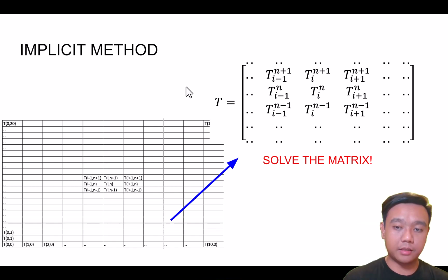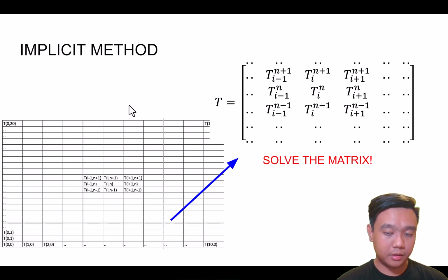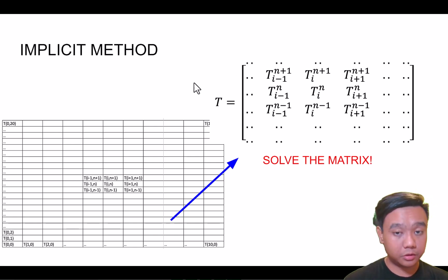But the implicit method will be faster to get the whole domain compared to the explicit method one by one. But for the implicit, you need a huge matrix to solve. Of course, you cannot do it manually, and in CFD we will need more memory to store this matrix. So it is very important from a practical point of view, but we will discuss it later.